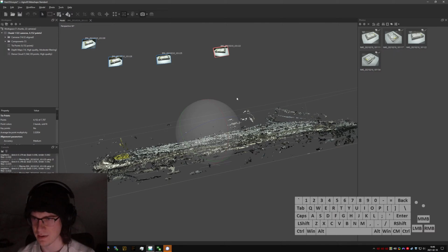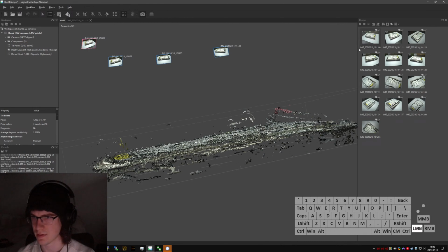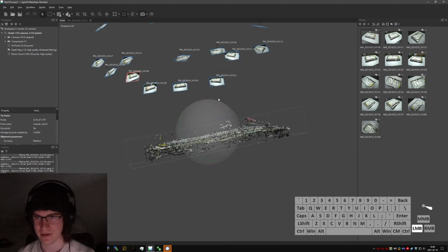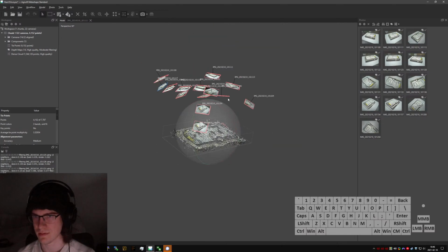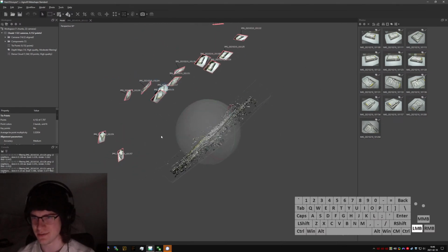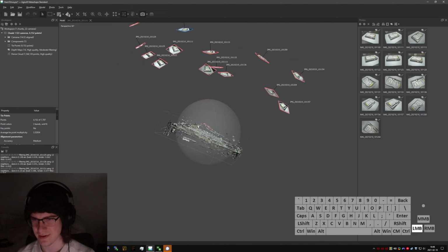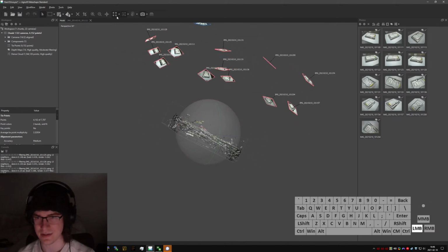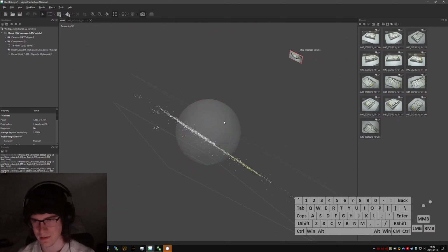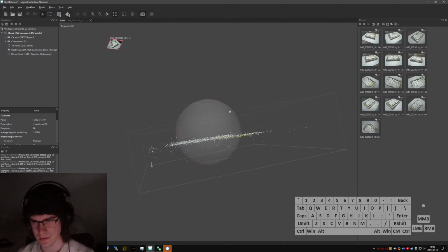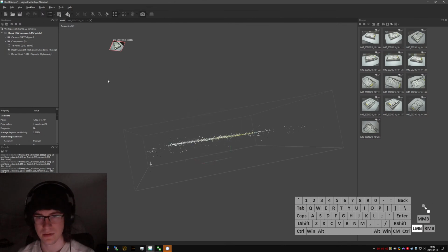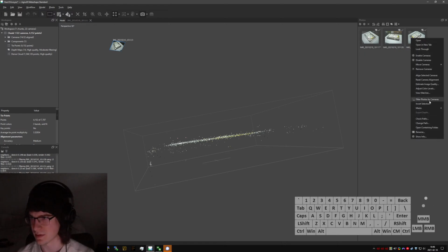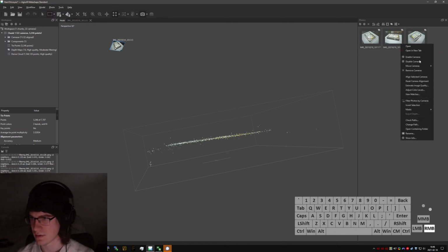You know what? I think... hang on, if I select by points and grab these guys and say filter photos by point. Nope, captured by like half of them. Okay. Actually, which half though? Oh no. No, it's referencing all of those. Garbage. Okay, well, let's come back to tie points then. And let's grab these two points, filter photos by tie points, and disable these guys. And disable those.